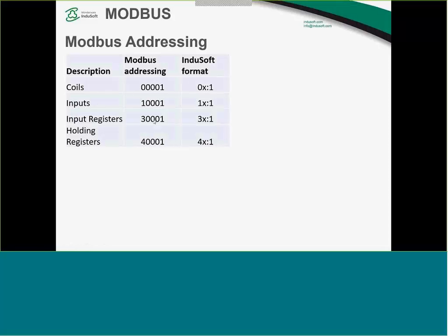So you take 2 of these words and make a floating point with 32 bits, or a double word, or, depending on the manufacturer, they swap the little endian and the big endian thing. Okay, so you have the smaller word on the left and the larger one on the right, or vice versa.